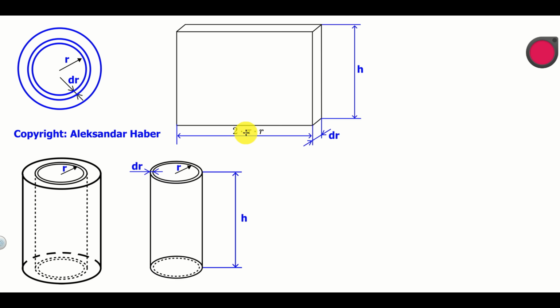This formula for the length is obtained by applying the formula for the circumference of a circle to the top circle of the shell. Namely, we know that the circumference of a circle is 2 multiplying pi multiplying r, and consequently we obtain the length of our cuboid. Next, let's derive the expression for the moment of inertia of our shell for the z-axis.